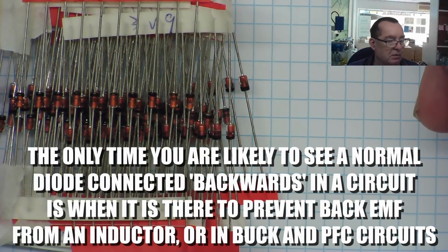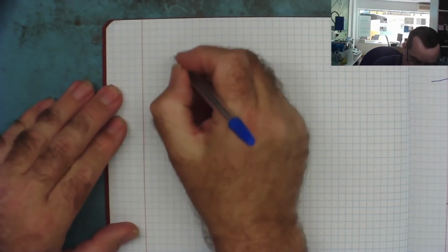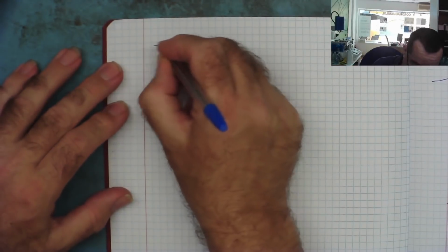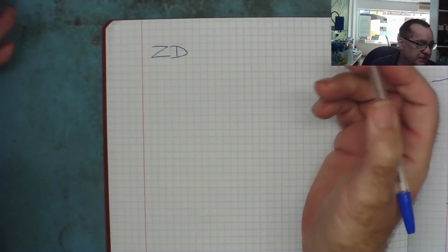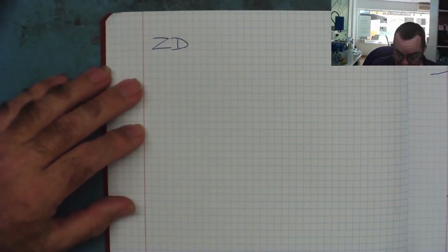And the second one is the marking screen printed on the circuit board. Often you'll find a Zener diode on the schematic or on the silk screen printing on the PCB marked as ZD. So ZD1, ZD100, ZD8 and so on. So that's a good indication that it's actually a Zener diode.